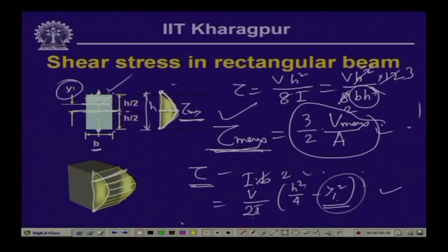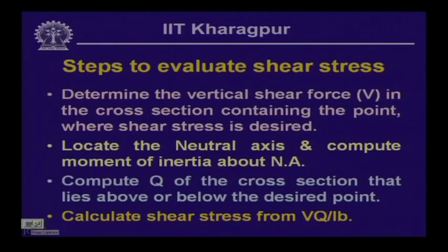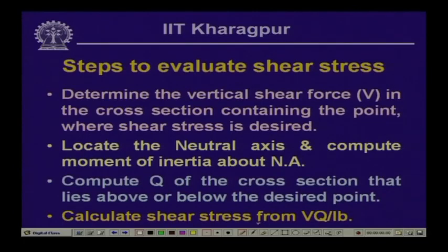Now, one aspect to be remembered is that we really do not bother about the sign of the stress as such. We consider that the direction of the shear stress is along the direction of the shear force. From the shear force diagram, we know the direction of the positive or negative shear, and accordingly we take the direction of the shearing stress as well. Now, with this background, let us look into the steps that we need for evaluating the shearing stress at a particular point.